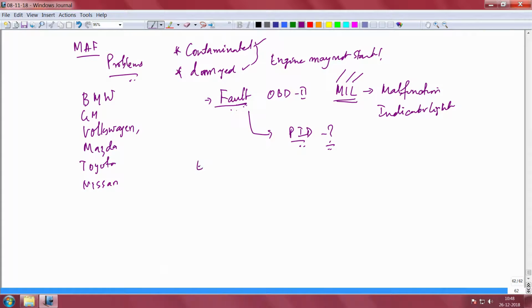If you take a car or a vehicle, we have the engine, we have the chassis and we have the body. The engine part was also called the powertrain, right. So, the actual power coming from the engine, and therefore it is called the power part, and then the chassis part and the body part. Therefore, since there is a P here, you will see that the OBD2 code corresponding to anything with respect to the engine will start with P.